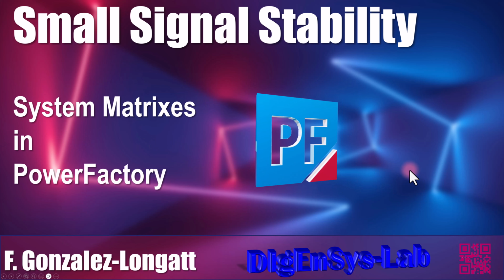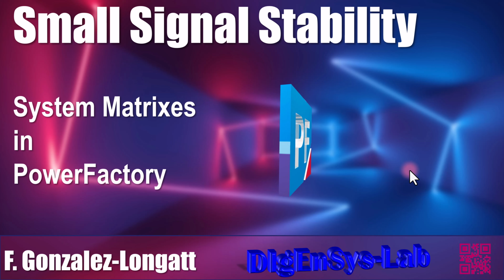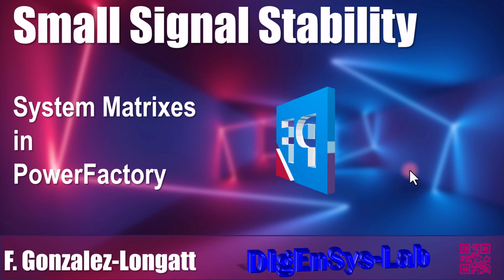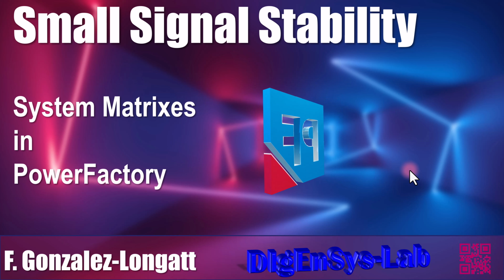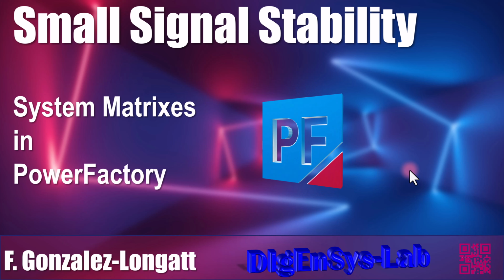Well, this is the end of this video. In this video, I try to explain or try to answer one very useful question for many people regarding the system matrices inside the DIgSILENT PowerFactory. And just to conclude, in this video, I show you the state space representation. That representation is where you can find matrices A, B, C, and D. But inside the DIgSILENT PowerFactory, for several practical reasons and the way to obtain the numerical state matrix, you are able to obtain the matrix A, the state matrix.